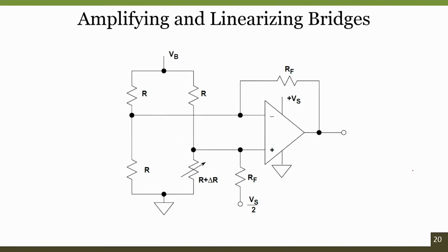So, as we discussed, in order to meet the properties of the next subsystem, the input impedance of the next stage should always be higher, so that no current will be drawn from the preceding stage. So, in order to have a very high input impedance by utilizing operational amplifiers, if we connect the output from the preceding stage directly to the input terminals of an operational amplifier, it will have a very high input impedance, so that no current will be taken from the previous stage, which means from the sensor side. Otherwise, the current drawn from the previous stage entirely depends upon the input impedance that we have designed.